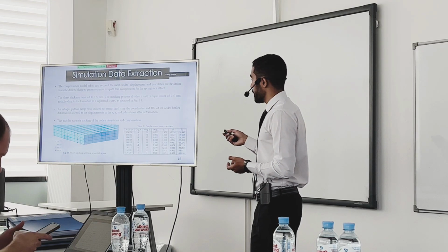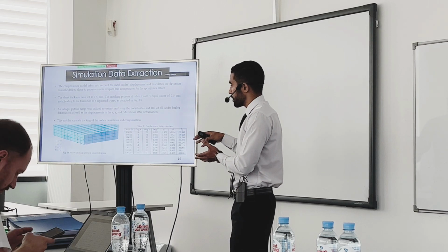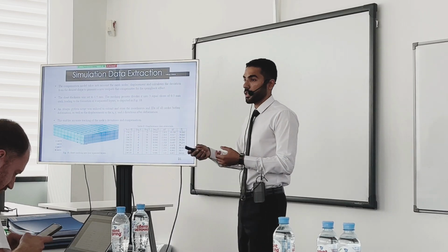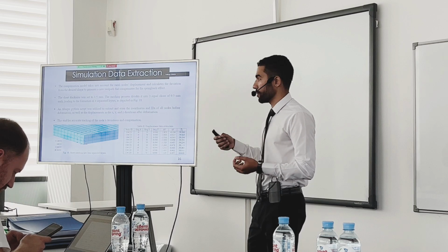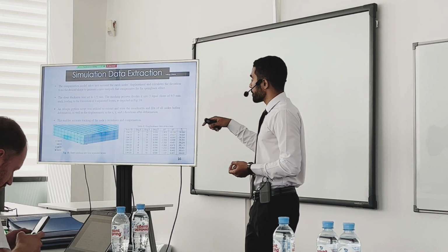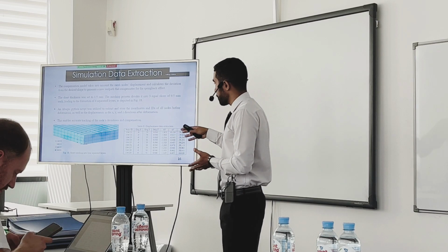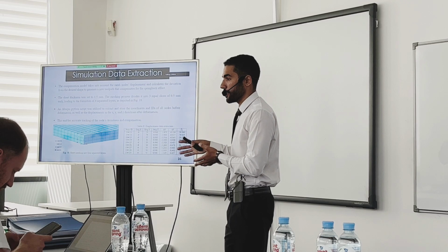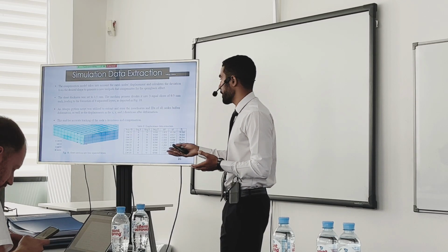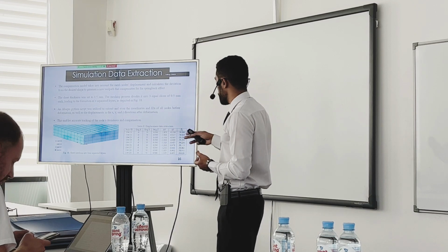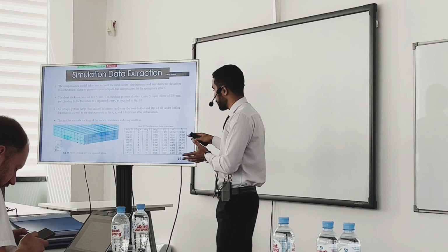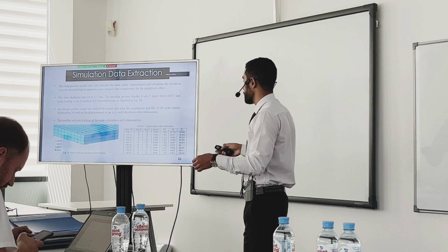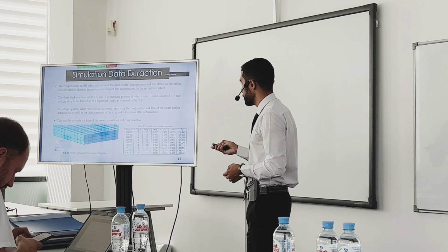So from the simulation data, as I mentioned, there is a meshing process of the sheet when it's in the undeformed state. In the meshing process, the meshing generates some elements and some nodes for each particle, I would say. This node is assigned a node ID. In order to track these nodes, I need to store these node IDs matching my toolpath. The results can be presented in this table. This is before the deformation. For each toolpath point, I need to get a specific node ID that I will track later.